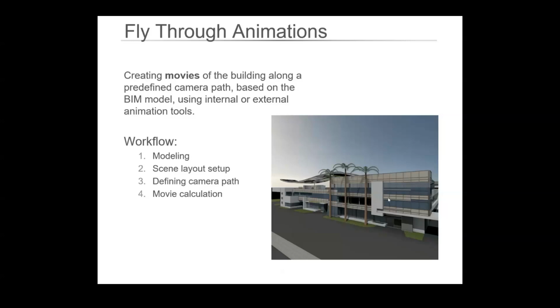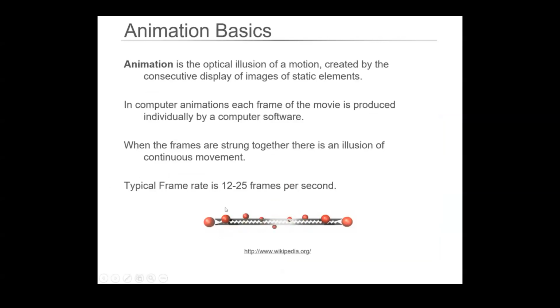Things to keep in mind there are time and how long you stay at a camera view, or the distance between cameras, because if you set it too quick, you just click the go button and it goes really quick, and you haven't had a chance to see it. So just set it, give it some time to rest at each camera stop, and then you'll get a nice smooth view where you can take in the whole building.